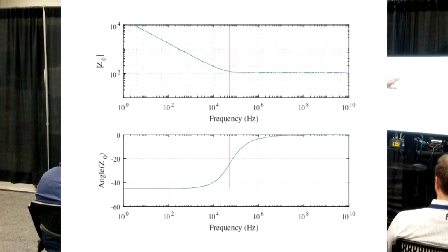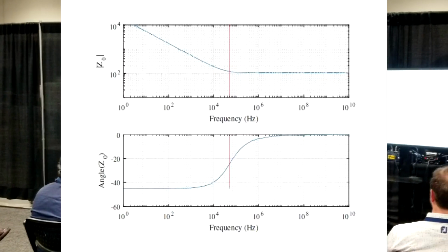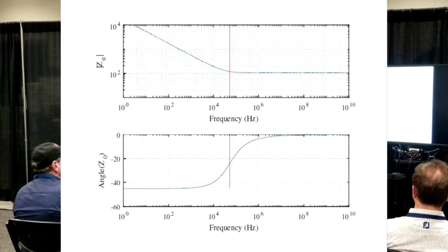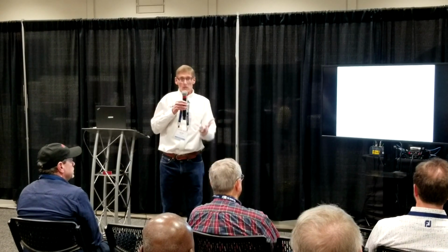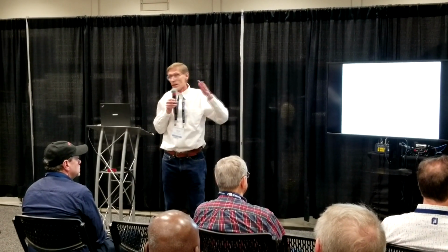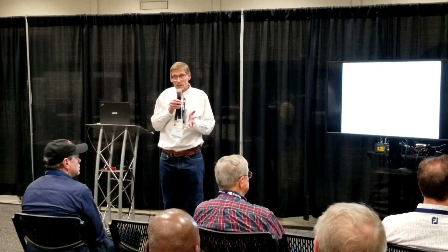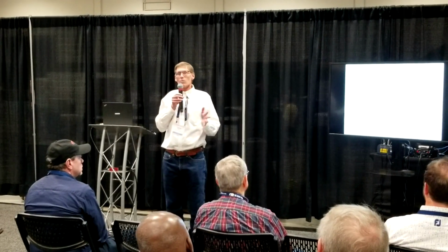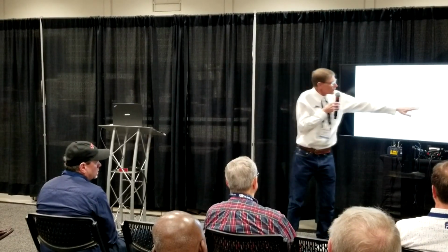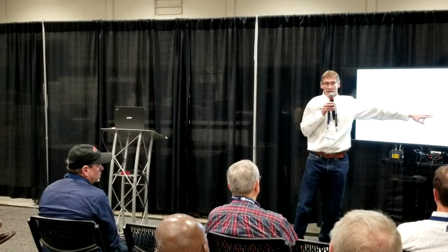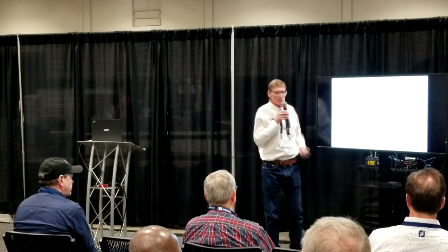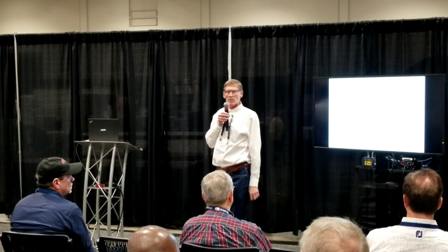But again, you see the same fundamental characteristic. Now let's look down here a second. We got a phase angle. Remember I told you the phase at RF is 0 because we're in resonance and the phase angle disappears? In audio, we can't do that. Guess what happens? When you look at a cable sitting in an audio system, say a speaker cable, and you measure it, the phase is 0 out at RF, that didn't change. But what happens when we get into our audio range? We're like at minus roughly 45 degrees. What is a negative 45 degree phase angle?